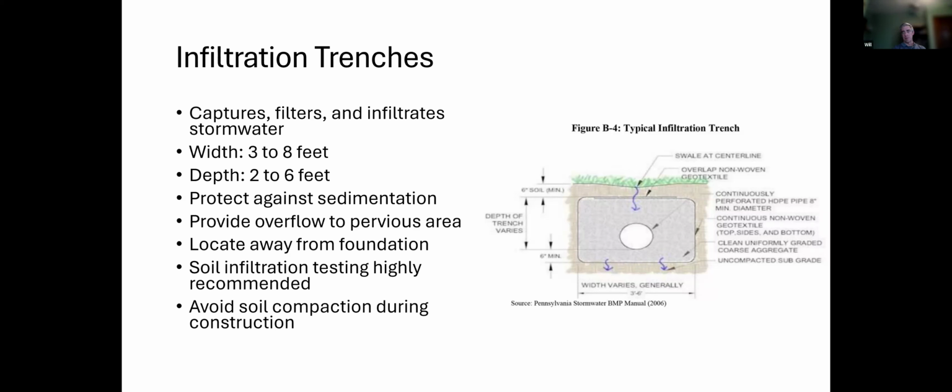So let's look at BMP number one, the cistern first, and figure out what size it needs to be. So this BMP one is capturing half of the runoff from the 400 square foot garage. So it needs to be big enough to handle 200 square feet of impervious area. And in Appendix B, all of these calculations are already done for us, right?